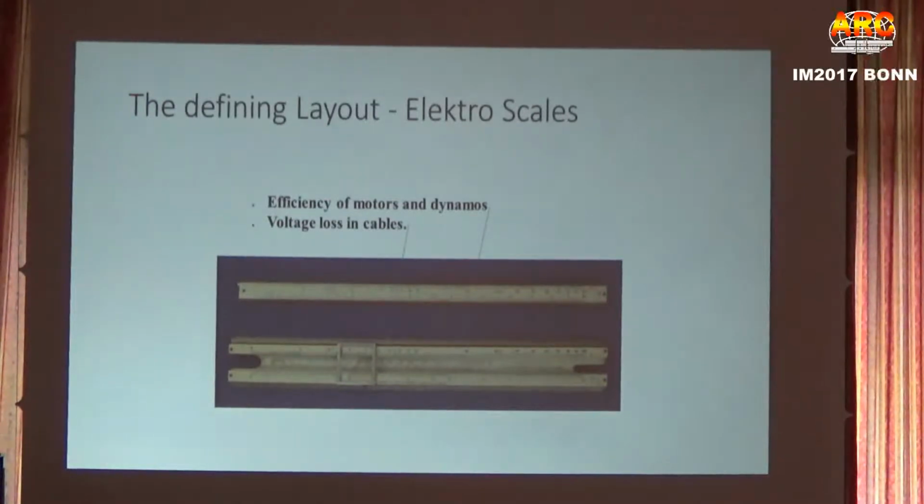Also, in electrical engineering, you have a thing called power factor. That is, the apparent volt amps is not what actually creates power, it's kilowatts. So you can measure volt amps, and it could be, say, 1,000 volt amps, but you actually deliver and get charged for kilowatts, which may have only been 850.